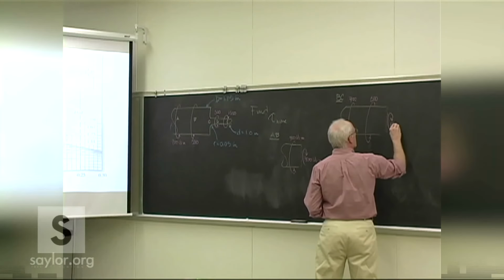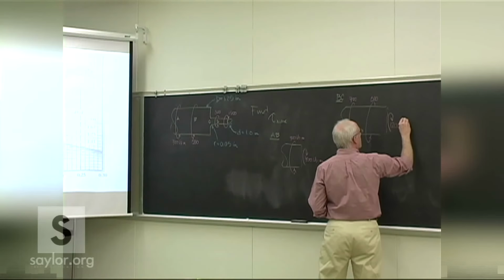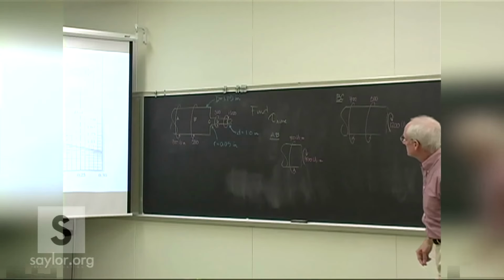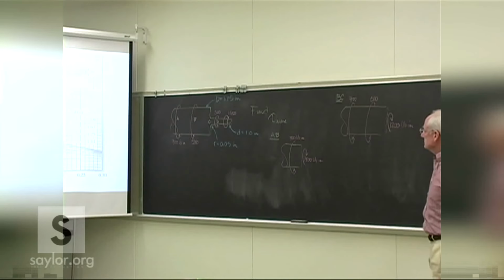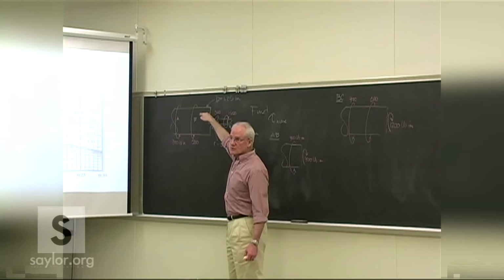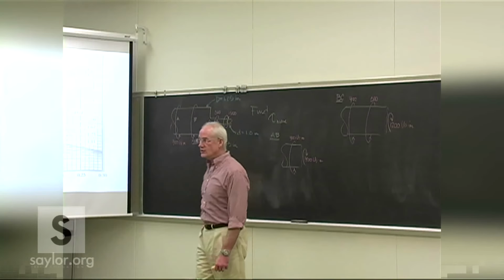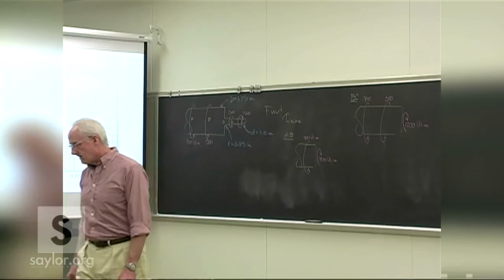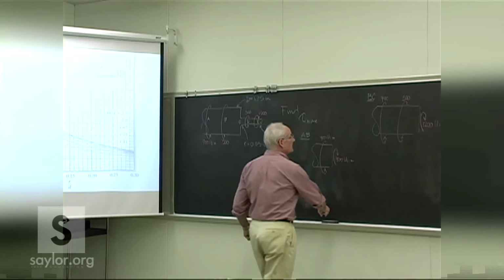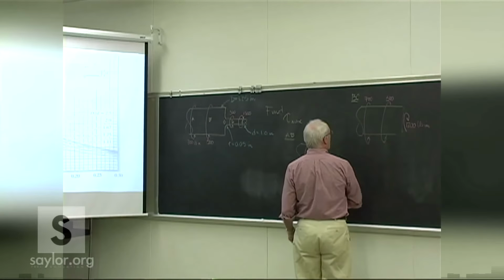So you know the internal load there is 1,200 pound-inches. And we only do B up to C because that's one diameter. And then there's a transition at C that could be the critical point. Actually, the 1,200 will take you all the way to D.